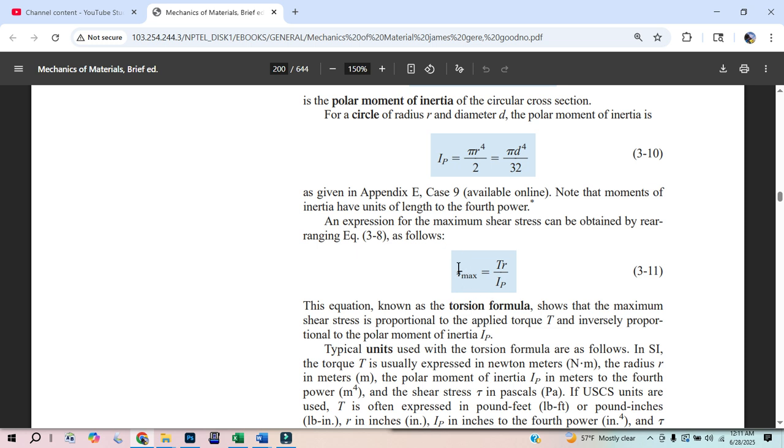So that's where this shear term should jog your brain to be like, oh, this is the material we're using. And that's not 100% true. It's going to be the force over that area no matter what material you choose. It's just that materials will have a max shear stress. So that's a better way to say it.